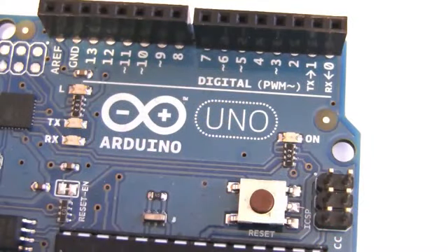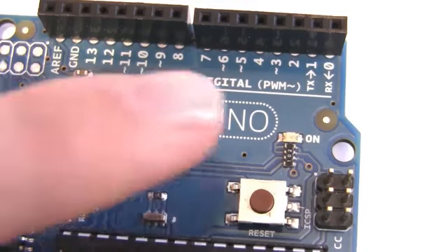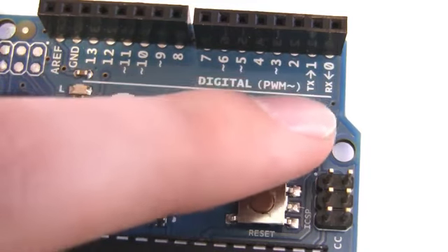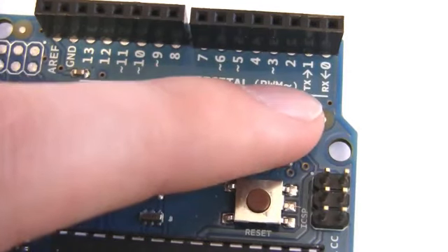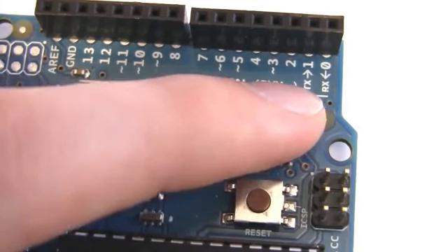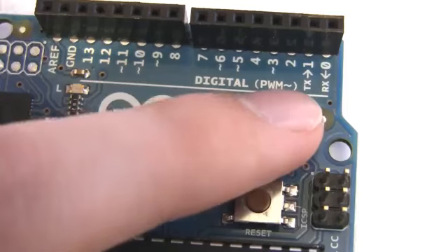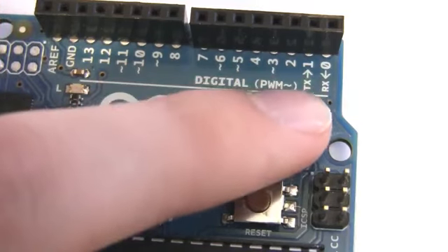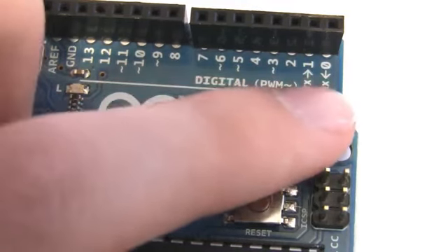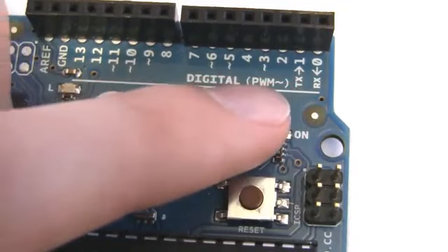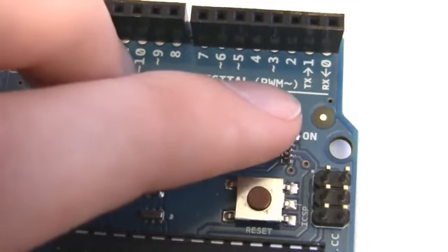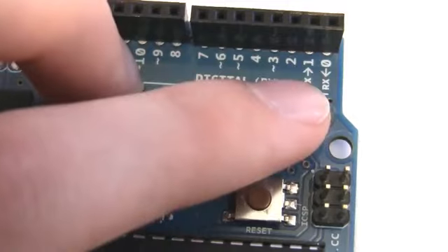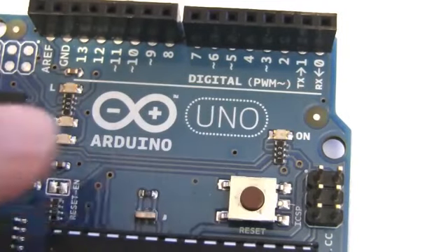Before we actually start communicating with the computer, let's talk a little bit about how we do this with the Arduino. If you look at the Uno, you'll see that there's a TX and RX pin on digital pins 0 and 1. Now you can use digital pins 0 and 1 while you're running your program for input and output. But during programming, these pins are multiplexed to be used as the programming pins for the Arduino. The RX pin is the receive, the TX pin is the transmit. When we call serial functions in the Arduino programming language, we're using these pins to talk back and forth between the computer and the Arduino.